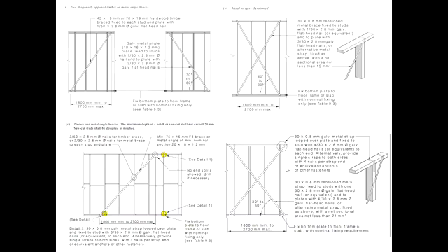So that's the steel brace that connects the stud to the top plate. So there's one single element. And then this is another possibility. It's a much stronger connection with two elements. So first you've got a tie that connects the top plate to the stud. And then there is the steel brace, the strap, which is a separate element, all right?